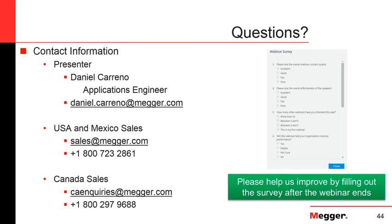And for the battery to be kept in a fully charged condition, the charger has to maintain the battery system at a float voltage. And that float voltage is the voltage needed, again, to maintain the battery in a charged condition. Because of that float voltage that the charger is applying, you'll have a small current flowing in the system to maintain the battery in a charged condition to compensate for the self-discharging of the batteries. So that is the float current, and you should take that into account when measuring the resistance.